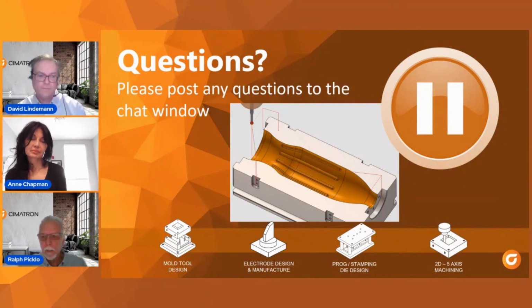So let's see. Dave, you might have to answer this one. Brad, can you check and adjust multiple pockets at the same time? I know we can check multiple pockets. Dave, what do you think on this one? If they're programmed on the same NC sequence, that's what it sounds like, they're going to use the same tool. The tool will have that same wear offset. So okay, from that perspective, you could do it. The question is, are they all the same? Do they have the exact same difference pocket to pocket to pocket? So that would be the risk you take, that one is less, one is more.